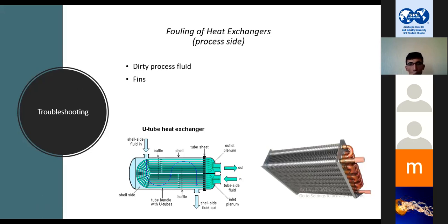Nitrogen coming back from the dryer brings some small polymer particles. We call them fines, and those fines can collect on the tubes and fins of this heat exchanger. By and by, we had to dismantle this exchanger as well and clean it, and washing it is also difficult because of so many tiny fins you can see there.